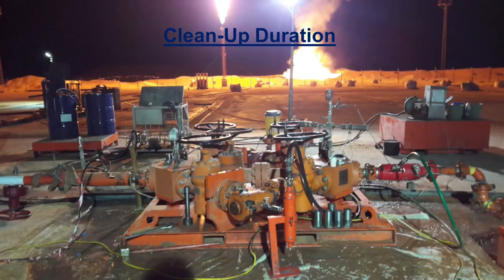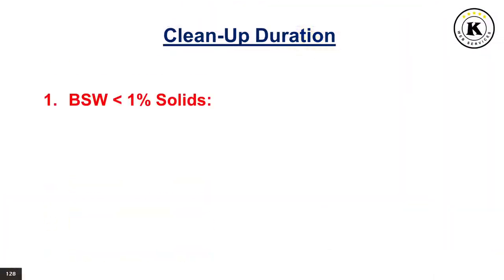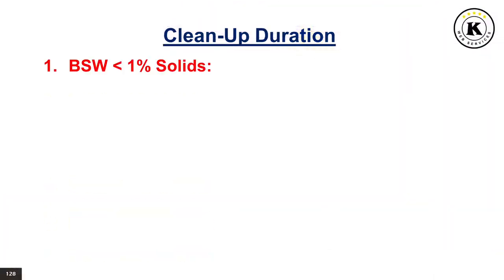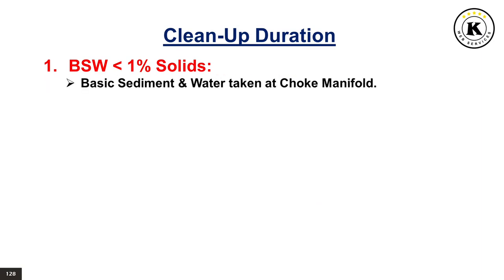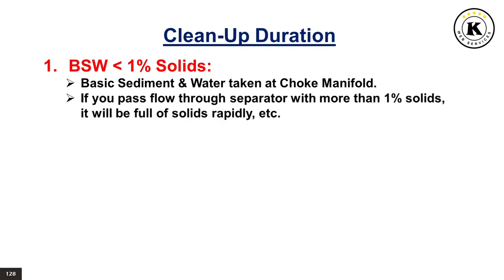Cleanup duration. The estimation of the duration of the cleanup period, or when the well is producing clean hydrocarbons, depends on several criteria. 1. BSW less than 1% solids. The basic sediment and water is frequently taken at the choke manifold. If you pass flow through a separator with more than 1% solids, it will be full of solids rapidly, etc.